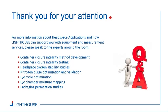If you read the language in USP 1207, they say that with your initial CCI qualification, the chapter says that you need to demonstrate that your test method, well, first of all, you have to determine what they call the MAL, the maximum allowable leakage limit, and then you have to show that your test method will detect leaks down to that MAL.